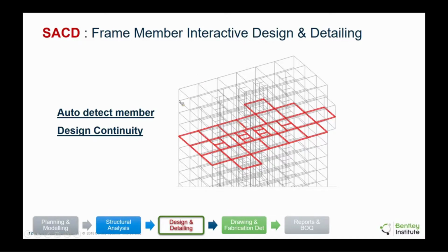Or similarly, if I have vertical objects, so if I have columns, instead, of course, you'll appreciate each of them is a different member number, but the software will automatically identify that this is one column comprising different member numbers. It puts that vertical load flow or geometry flow in place, and appreciates changes in column size. So when it's detailing, it will reduce the number of bars. So it brings all of that accuracy and practicality, the intangibles that we talked about.